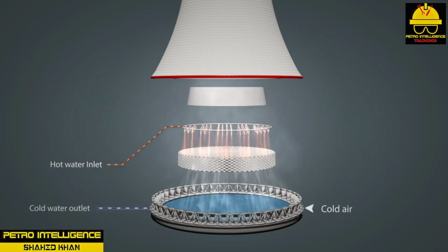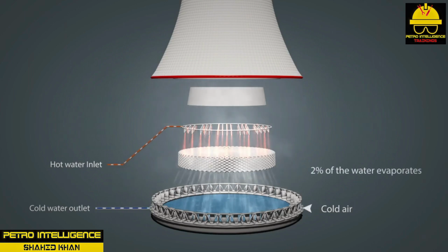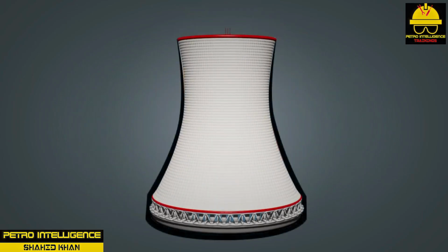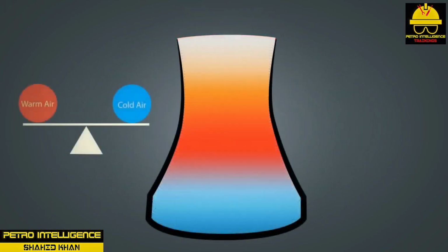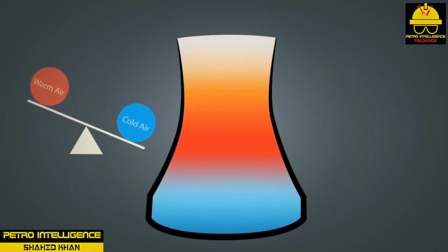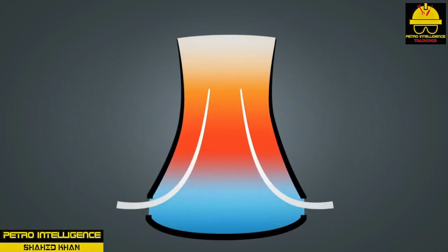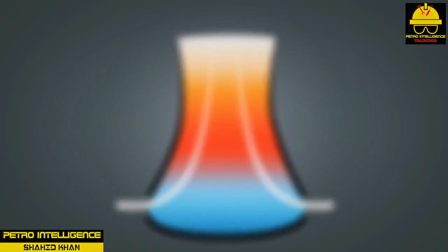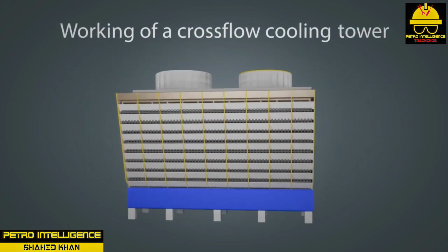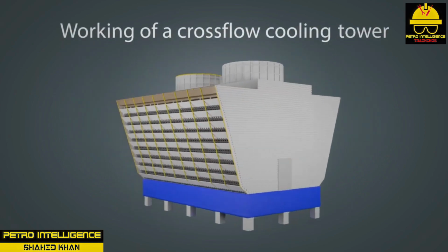Evaporation, which accounts for 80 to 90% of the heat loss, is the most critical factor in cooling tower efficiency. It is affected by relative humidity, that is the amount of water in a given quantity of air at a given temperature, wind velocity, and temperature. Other factors that affect cooling tower efficiency are tower design, water contamination, and equipment problems. Cooling towers can be described as psychrometry devices. Psychrometry is the study of cooling by evaporation.